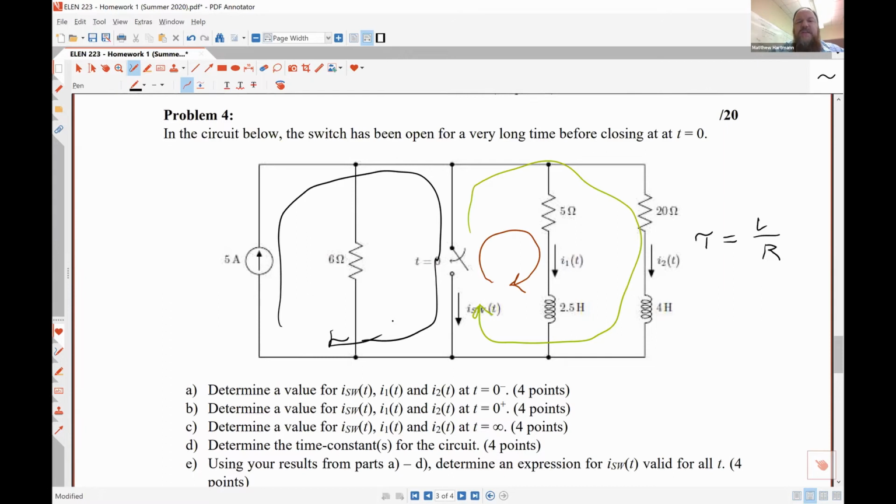So based on the direction we have, it should be something like 5 amps minus whatever the initial condition on I1 is, e to the minus 0.5t, minus whatever the initial condition on I2 is, e to the minus 0.2t. Make sense? Yeah. Cool deal. I know you guys weren't the ones asking the questions, but maybe you had a question and perhaps I have answered it.